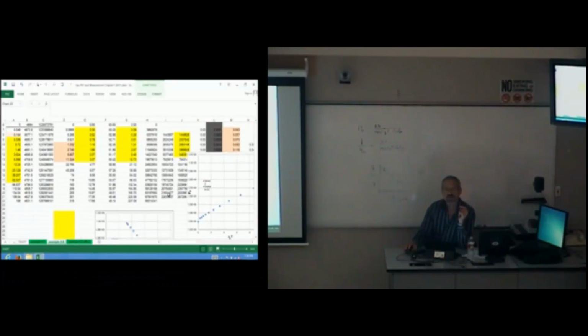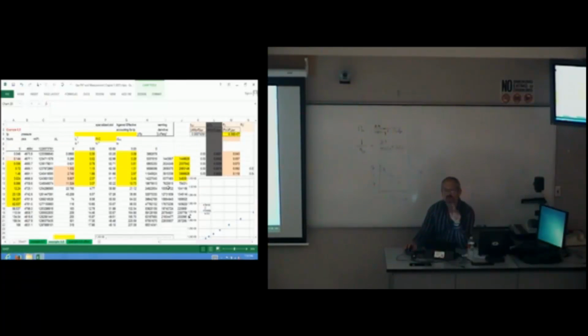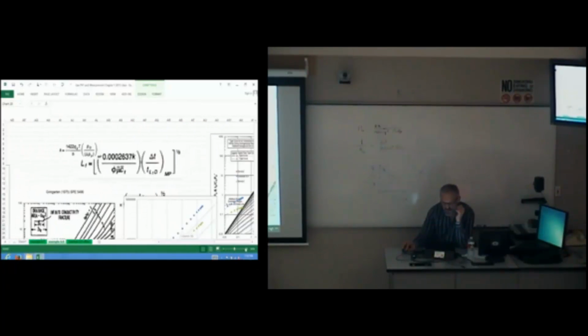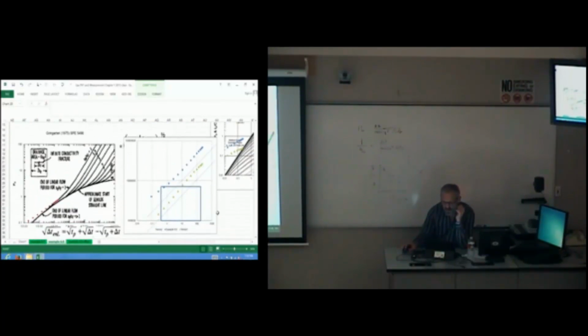I'm glad you asked that question, because we can do the same thing. We have already calculated a pressure derivative over here, and it wasn't very conclusive. I think these are both half slopes. I've changed the data a little bit. And if I was just to base it on half slope information, let's get rid of this box right here.